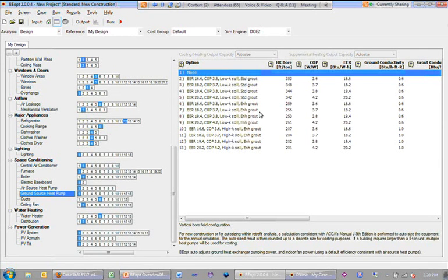So the biggest effect of improved conditions may be in terms of reducing the cost of the installation as opposed to improved performance. And so that's something to bear in mind, that the sizing technique actually sizes to have the right ground heat exchanger capacity.